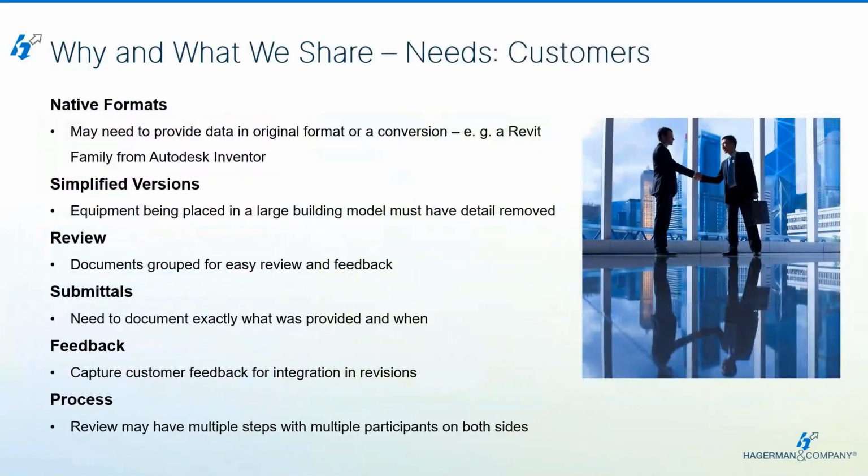So kind of breaking these down a little more, again, native formats, you might need to provide an AutoCAD drawing, an Inventor assembly. Sometimes, depending on the relationship, maybe you don't want to provide full detail to a customer because that would expose some of your intellectual property. If you sell equipment that goes into a building and it's eventually going to go into a BIM or a Revit model, all of that detail is just going to cause problems in your customer's model, so it needs to be simplified.